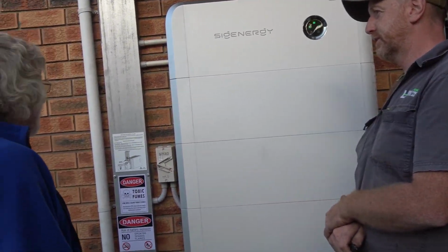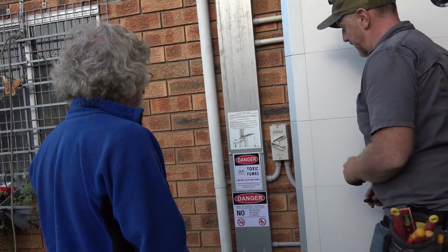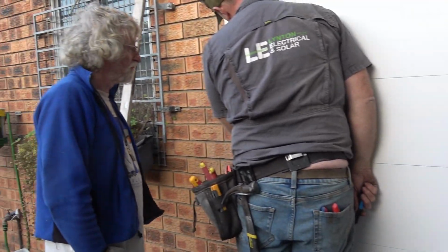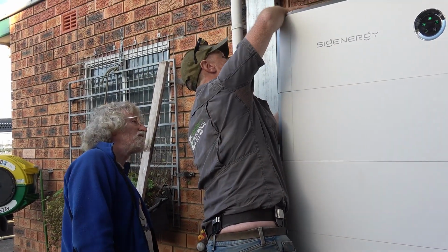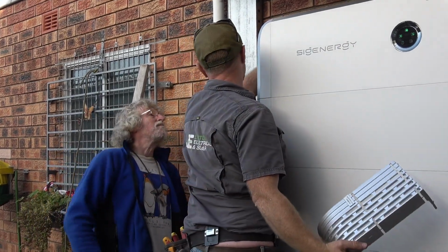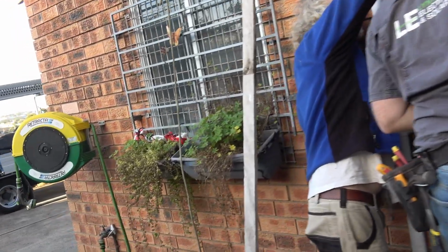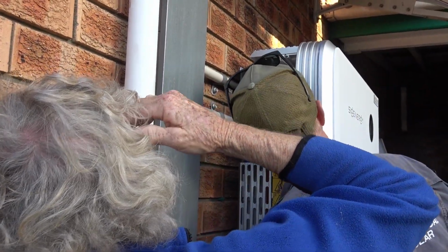Okay. Any other questions? How to turn it off? To de-energize the system, there is a full shutdown procedure here, but if you want to turn it off, you turn off that switch and you turn off in here, you can lift these covers up. There's a DC switch in there for the panel. Turn that off. So the top one is the panels switch. No, this one here. See that one there? Yep. That's the one for the panels. It says DC switch.